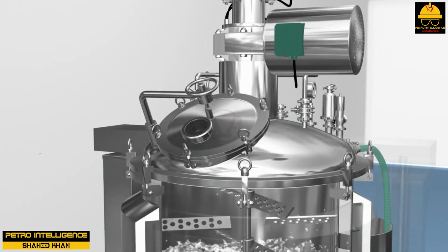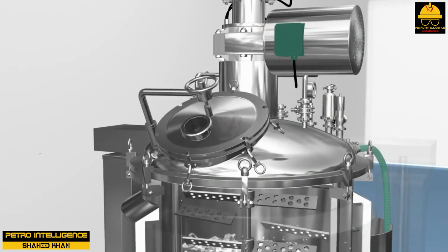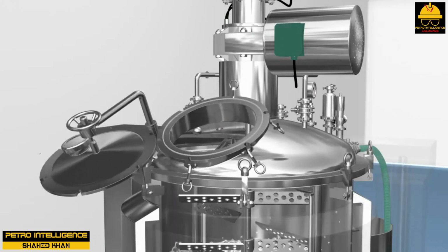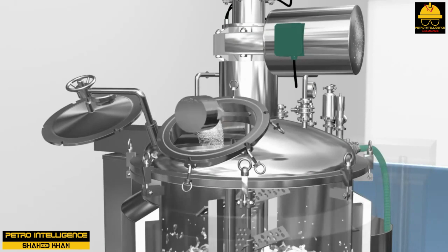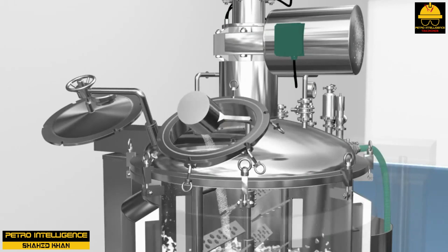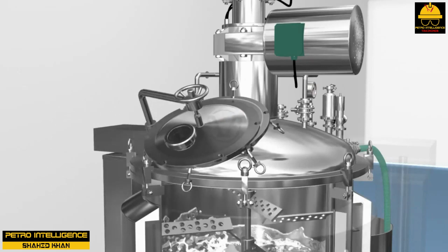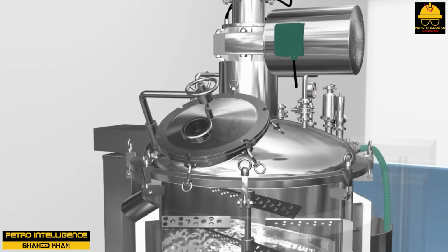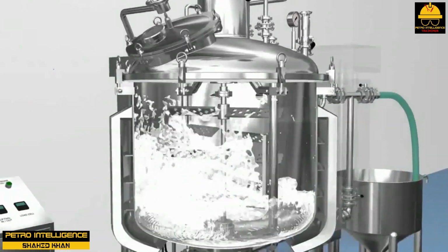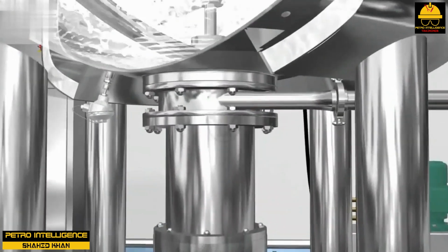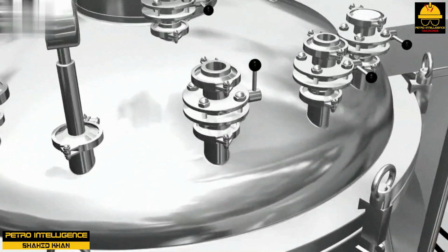The basic features of a stirred reactor are designed to provide long reaction times, mechanical agitation, and a method of cooling or heating the reaction. Stirred tank reactors are used for liquid-liquid reactions, gas-liquid reactions, and liquid-solid reactions. Stirred tank reactors are used for reactions that require a relatively long reaction time and for reactions of slurry or thick liquid in which mechanical agitation must be used to provide a uniform reaction mixture.